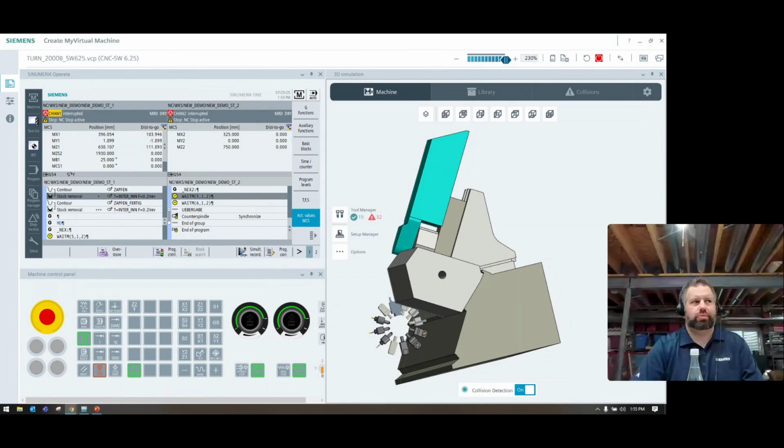If you can imagine what we're doing, we're moving effectively the X and Y linear axes as they're spinning around in a circle. That's simulating your spindle. So however fast those axes can move are going to be your biggest limiter. So when you're in small features, this is super slow. It is not worth your time.